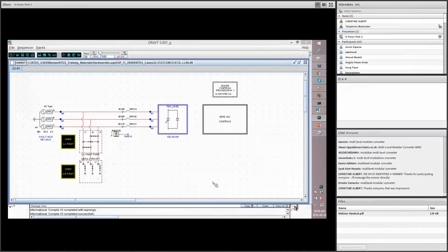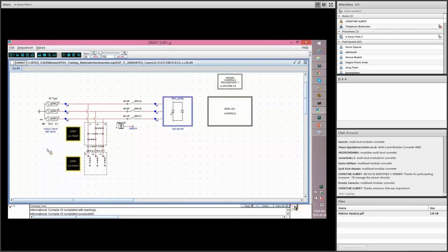So here is the standalone simulation case representing a simple STATCOM system. We have an AC side circuit which represents your AC system, and I believe many people here are familiar with the technique of representing the AC system strength by using a certain combination of R and L. So in here we set the impedance of a three-phase source to represent the system strength of 667 MVA.